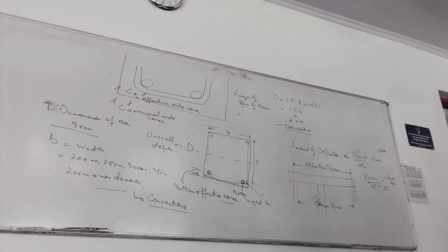So you can get, do you put the beam in this direction or in this direction here? This direction, 6 meters. If you put the beam in this direction, just by visualizing, this is 10 meter in this direction. You can put a single beam in this direction. You will always have a connecting beam like this, then in the other direction. So the span is actually half there, 5.